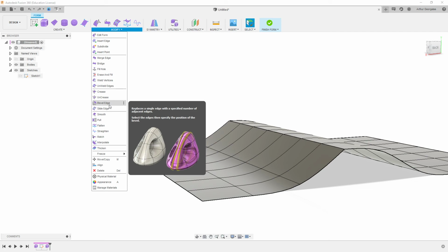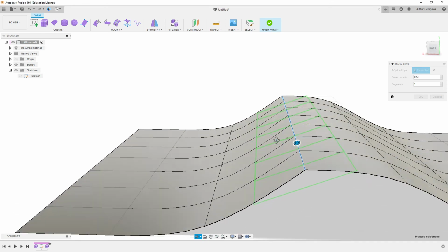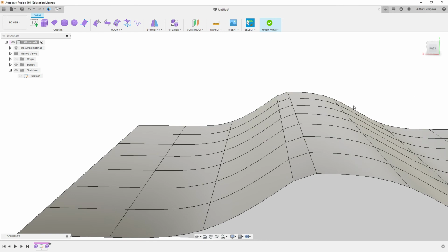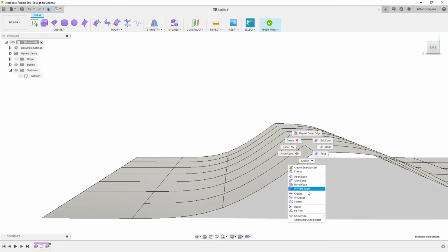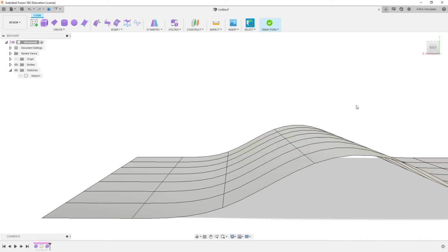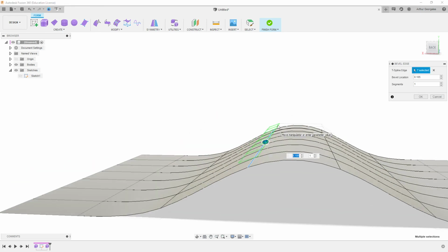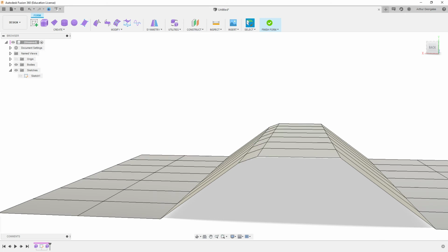Bevel Edge. I actually prefer, instead of beveling an edge, to use Insert Edge and move it close, because what bevel does, it actually, sorry, that's still creased. So what we'll do is uncrease. What Bevel Edge does is it puts an edge somewhere on both sides of your line, and it deletes the original line. So if we push this up here, we can see it's going to put a line here and a line there, and it's going to make that much tighter.